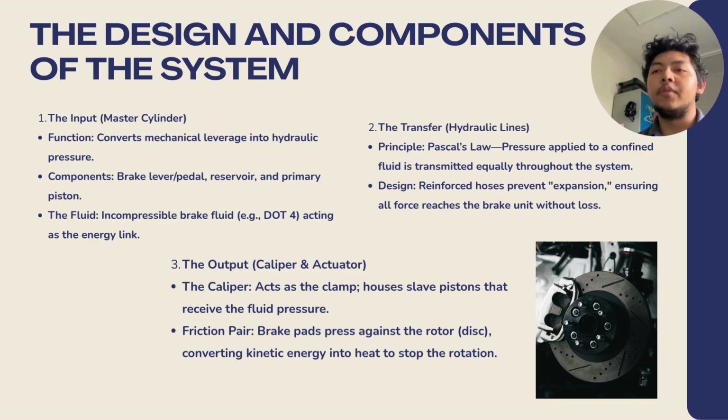Now I will present about the design and components of the system. First, the input or master cylinder. The function of the input is to convert mechanical leverage into hydraulic pressure. The components in this design are the brake lever or pedal, reservoir, and primary piston. The fluid present is incompressible brake fluid, for example DOT 4, acting as the energy in.